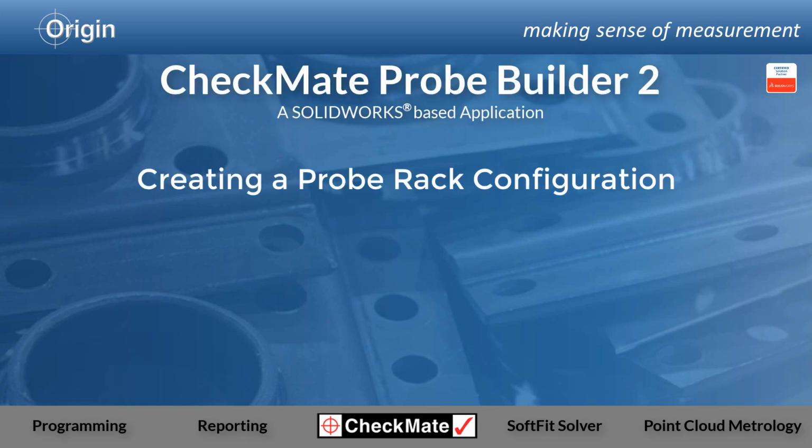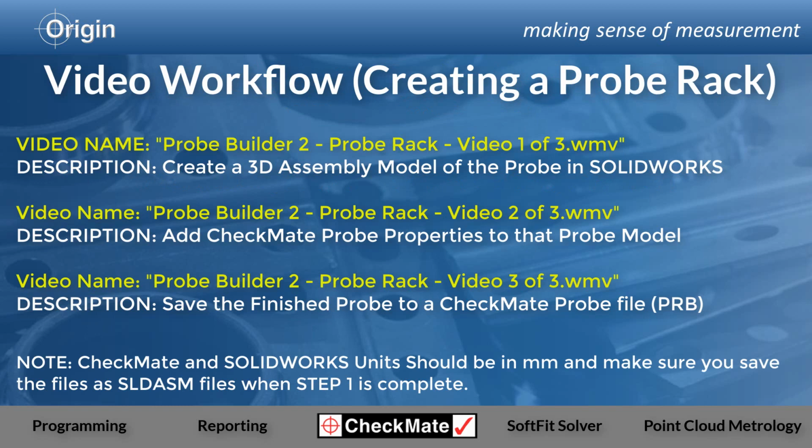In this video series, we will be reviewing the process of creating a custom Checkmate probe to use with the Checkmate programming module. The basic workflow consists of 3 steps. First, create a 3D assembly model of the probe in SOLIDWORKS. Second, using the Probe Builder 2 add-on, we add the Checkmate probe properties to that probe model. And finally, step 3 is to save the finished probe to a Checkmate PRB probe file.